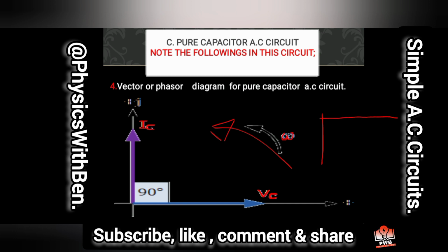We can equally draw this diagram like this. And our IC will be here, and our VC will be here. And then you can draw it this way. So it is not a must that you draw it the way it is appearing here. You can equally draw it this way. Good. The current is leading by pi over 2 or 90 degrees, while the voltage is lagging by pi over 2 or 90 degrees.